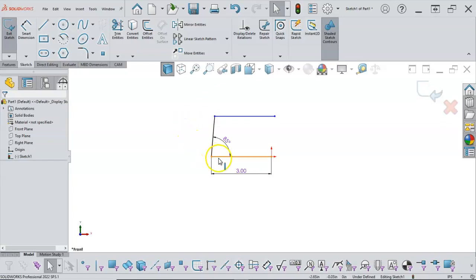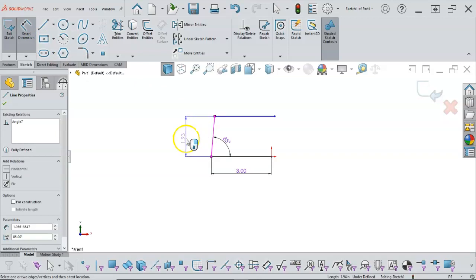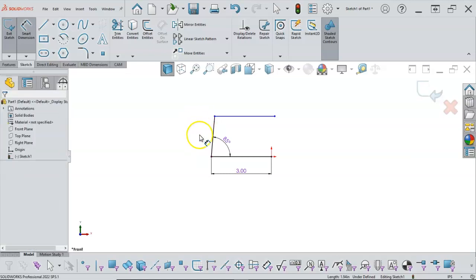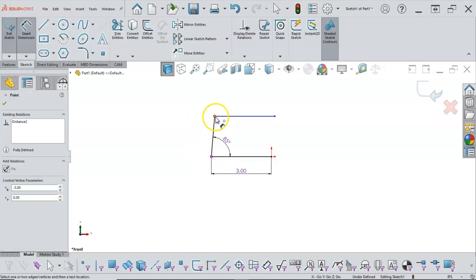So we did the between two. I did not apply to the object, so let's go to the Smart Dimension, and we'll go back to a vertical, which is really what we're looking for, the horizontal, and also, if I get it in the right place and got to kind of look for it, is the linear dimension following the angle. So we can get all three of those, and then all I would do is click and place it. And then last on the list is to put the two endpoints.